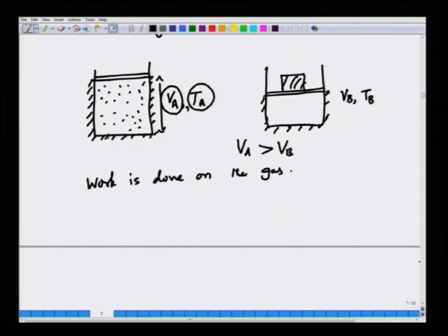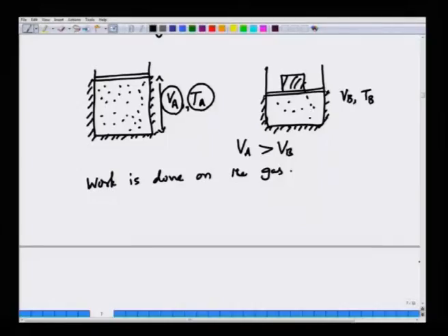Well, since you have completely insulated the system, this work that has been supplied to the system clearly has not gone to increase the potential energy of the system, nor has it increased the macroscopic kinetic energy of motion of the fluid molecules, because initially the fluid is at rest and finally also the fluid is clearly at rest.